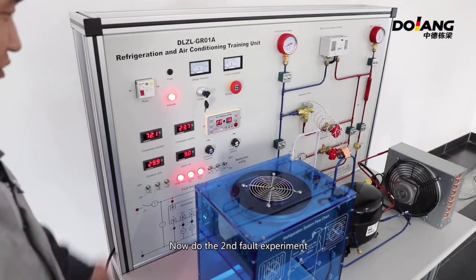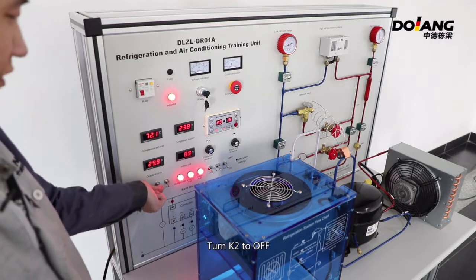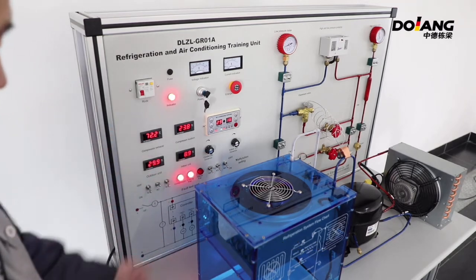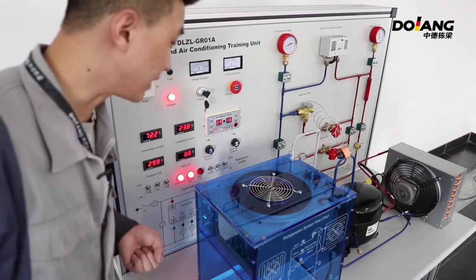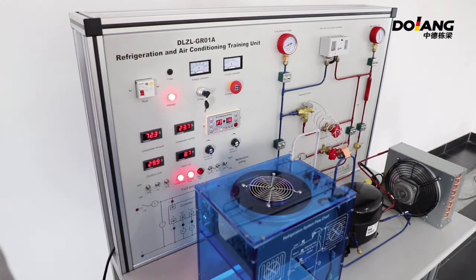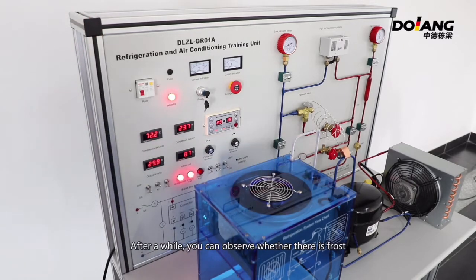Now do the second fault experiment. Turn K2 to off. Now the simulated indoor indicator is on, but the simulated indoor evaporator fan does not run. After a while, you can observe whether there is frost.